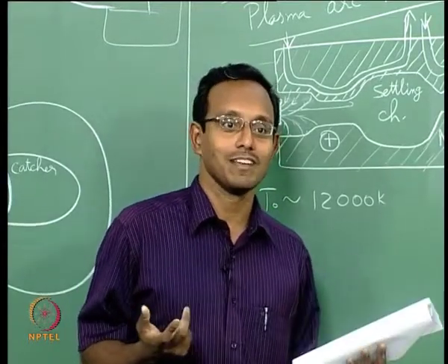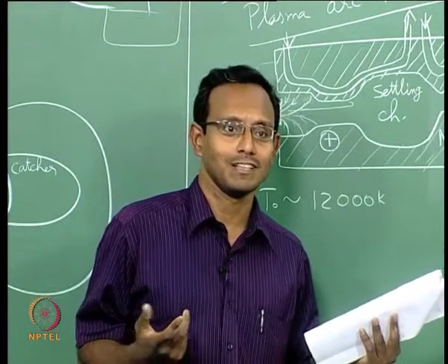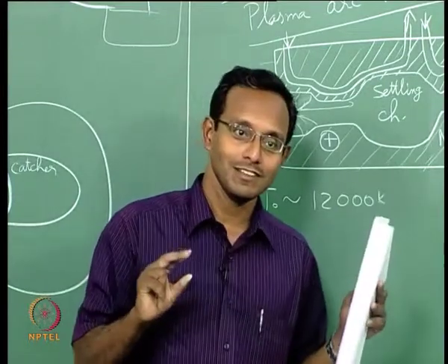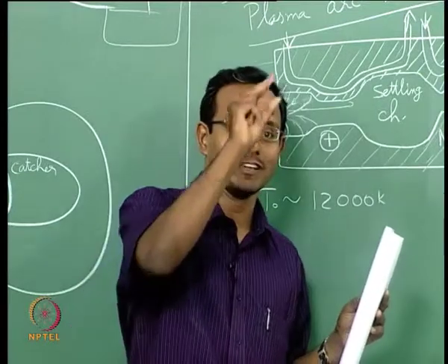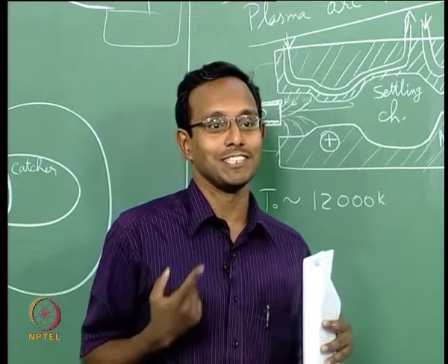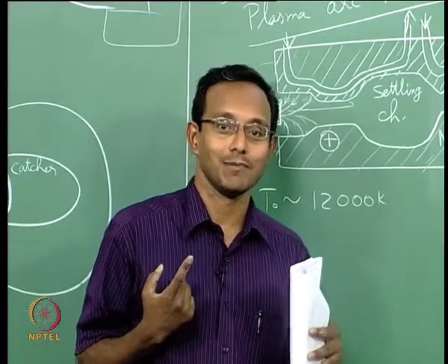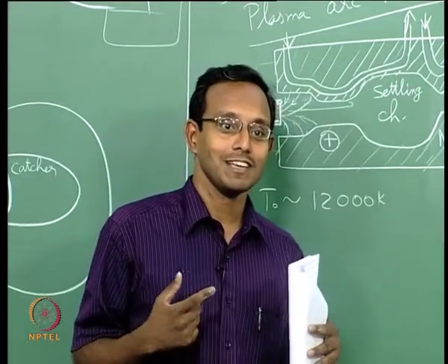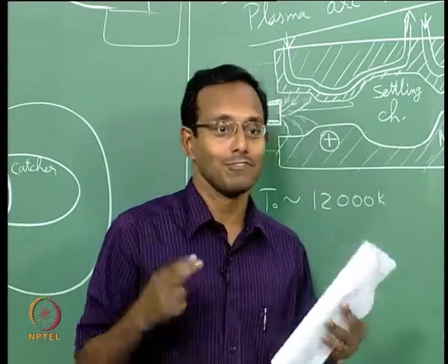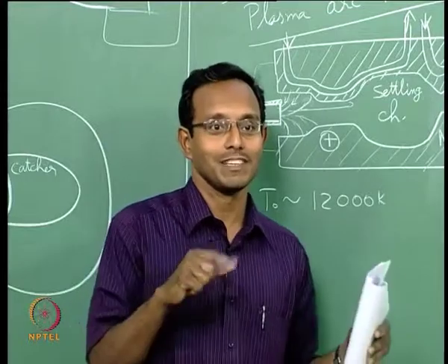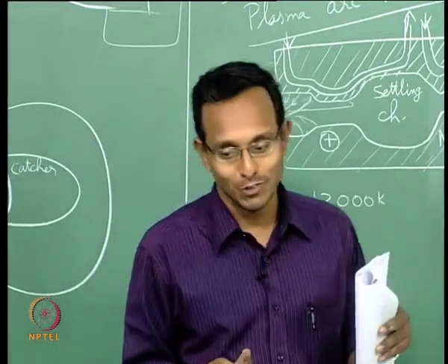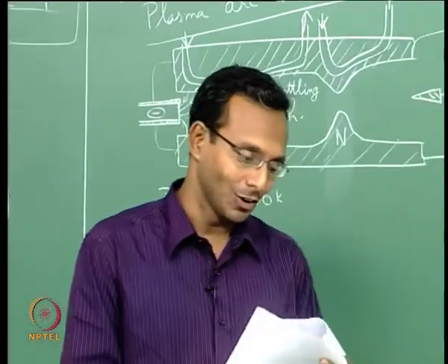What am I using here? Chemical power, chemical energy. Okay. It is propellants burning, creating thrust, and that is causing the whole model to be going very high. Drawback of this, it has to withstand the launching G values. Okay. The model should withstand the G values. Initially of course you should anyway design for, if it is high Mach number, the flow forces. More than that, now I have to think about G values. Okay. That is one more thing I have to think about, accelerating with a rocket.